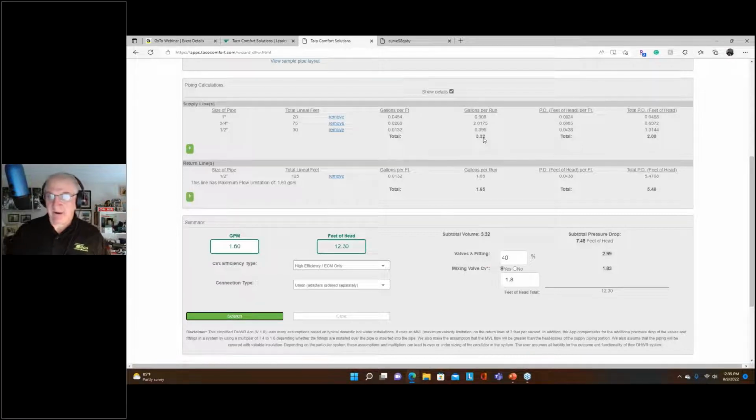Now, here's the thing about our smart plug for the Smart Plus E. That'll run that circulator in a 5 minutes on, 10 minutes off pattern. So it's going to run the pump for 5 minutes and turn it off for 10, on for 5, off for 10. What that means is we don't have continuous circulation. We've taken that contributor off the table. I'm going to run for 5 minutes at 1.6 GPM. So as far as when that pump turns on, I've got this line completely primed and ready to go.